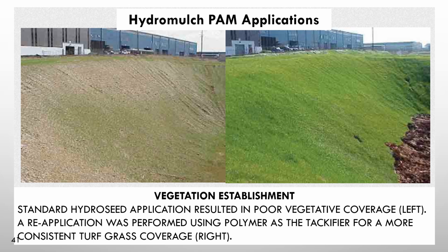You can imagine after we've done a hydroseed application, if you have a large rain event, we see this all the time where all that material that we've applied can wash down a steep slope. So if we use the PAM as a tackifier, we can hold that in place so that the roots have time to establish, and we can establish vegetation even if we have rain after our application. And again, going back to that USDA research, it's not just about holding the material in place. It actually improves soil structure, improves infiltration, keeps microbes, nutrients, soil, all of that stuff in place so we grow grass and vegetation faster and more efficiently.